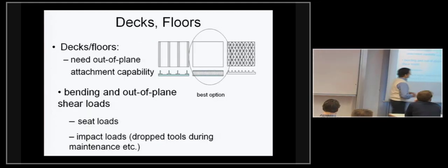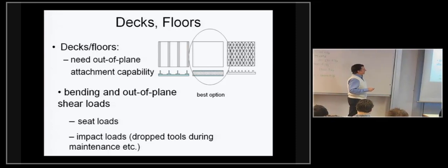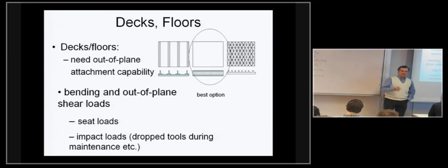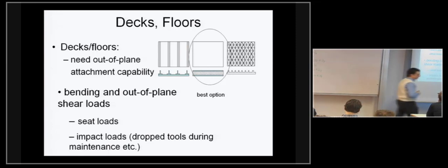Decks and floors are just glorified skins which can have different designs. Remember the stiffened design, the sandwich design, the grid stiffened design. And you can have both in-plane loads and out-of-plane loads. Walking loads being one of the significant ones, and seat loads being another in the floor. And of course, impact loads, dropped tools during maintenance, and so on. We'll cover impact in the second part of the course in very, very much detail.